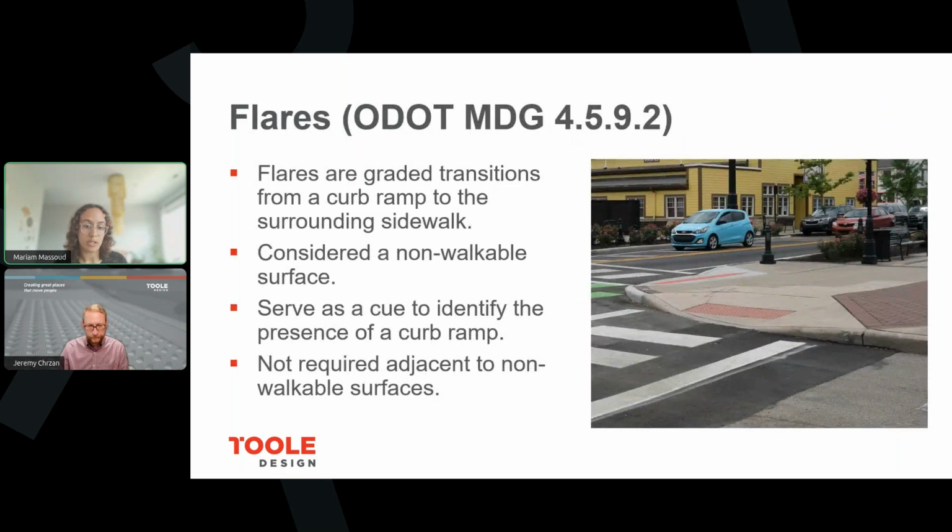Flares are another curb ramp component. So this is a graded transition that goes from the curb ramp to the surrounding sidewalk. And like we said, this is only required in some situations where the ramp is next to a sidewalk or walkable area. The flare itself is considered not walkable, so it's not part of the pedestrian access route, but it does serve as a cue to tell someone that there's a ramp there.